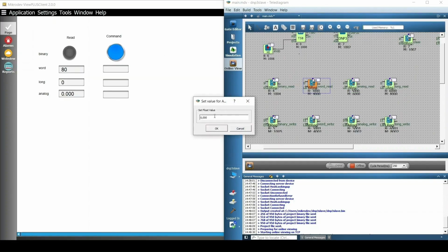A common expression for float value. Let's say the value is 10.5. As you can see, the value of 10.5 is transmitted to SCADA as unsolicited. We can change the value again. Let's write 8.4. The value of 8.4 is also transmitted instantly. Let's enter a large number into the long values. When I send the long value, we can follow that it is transmitted instantly.